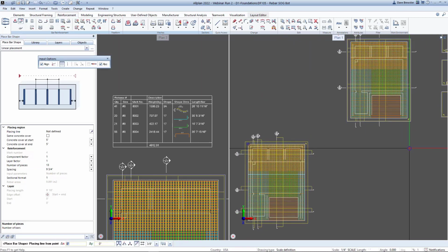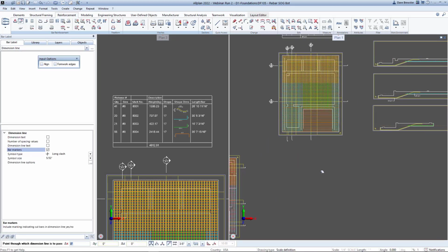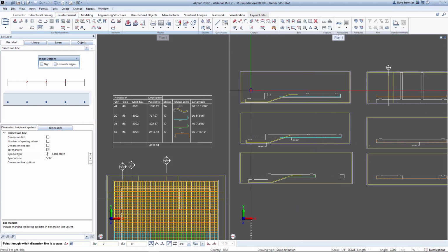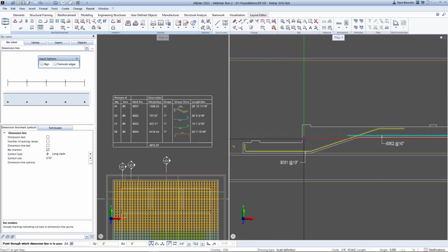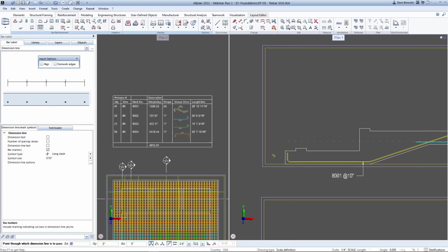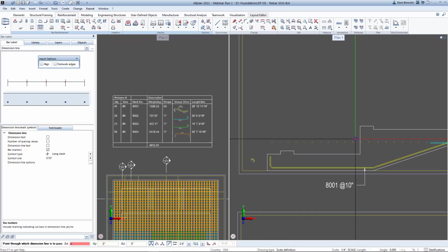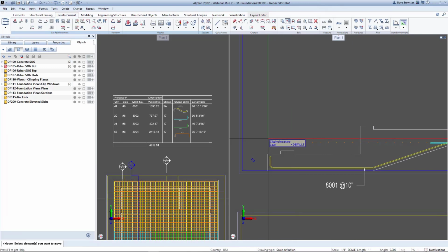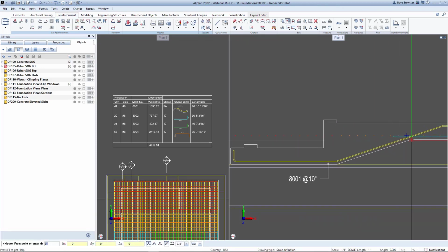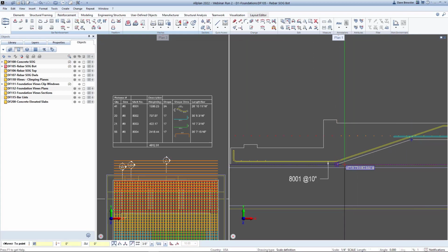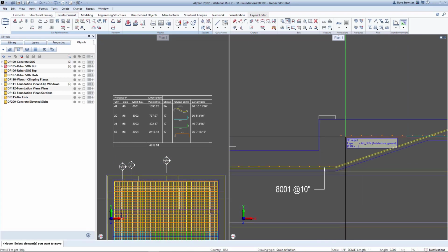So after I got these all dialed in with the spacing that I want, I'm going to go ahead and zoom in on the section cut that shows me where my range bars are. And you'll notice that they're not horizontally where I need them to be. They're up a little high from where they are. I'm going to do a simple move command. Move the first range down. And in our case, we're going to move this range from a specific location. Using tracking, I'm going to track it from there and down to there.